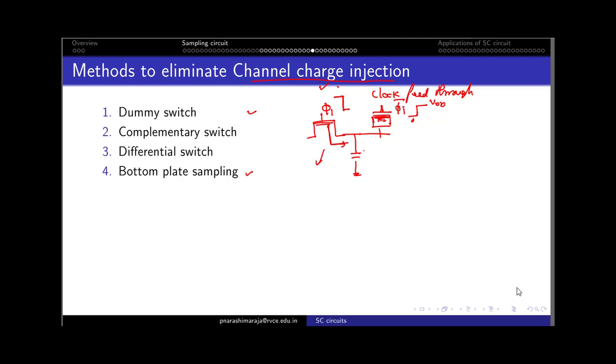Let me assume that the channel charge moving towards the source, or towards this Vout, is half the value of the channel charge I had under this M1 transistor. The moment this is turning off, I turn on the M2 transistor. This also requires some channel charge, which I take as delta Q2, and let me represent this amount of charge to be equal to delta Q1.